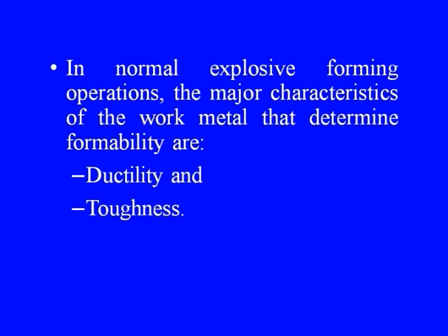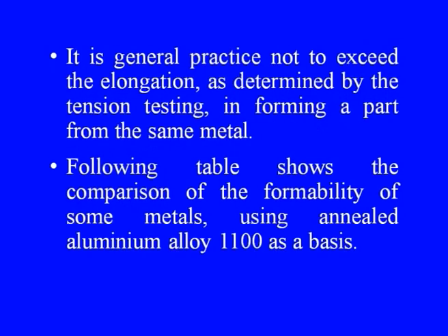In normal explosive forming operations, the major characteristics of the work metal that determine formability, as I have already told, are ductility and toughness. In general, the deformation should not exceed the elongation as determined by the tension testing in forming a part from the same metal.